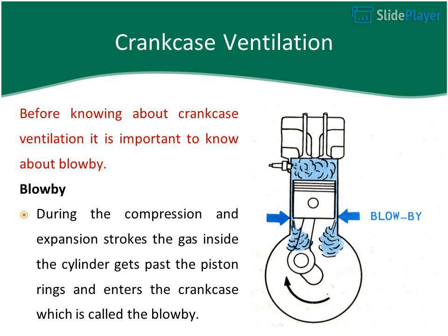Crankcase ventilation. Before knowing about crankcase ventilation, it is important to know about blowby. Blowby. During the compression and expansion strokes, the gas inside the cylinder gets past the piston rings and enters the crankcase, which is called blowby.